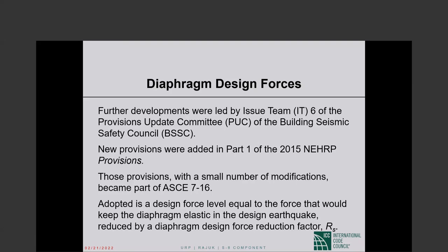Should I continue, Dr. Ghose? Yeah, please. Okay, so this is a big question. In a dual frame structure, most of the stories are extremely torsionally irregular, and the seismic force resisting system consists of more than two bays of moment resisting perimeter framing on each side of the structure, and in each orthogonal direction at each story, resisting more than 35% of the base shear. Can we still take the redundancy factor as 1.3 or 1?